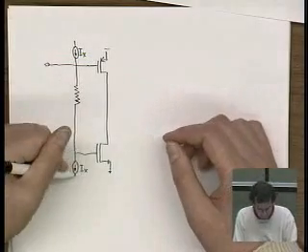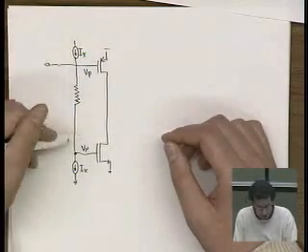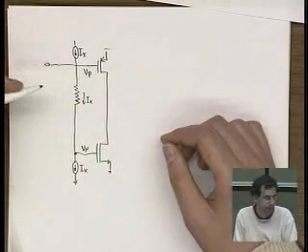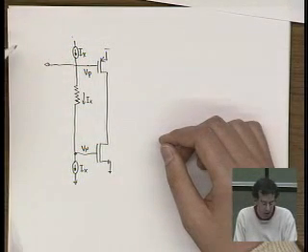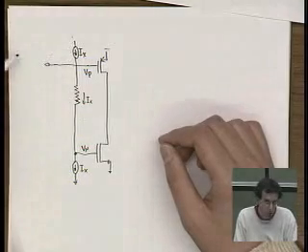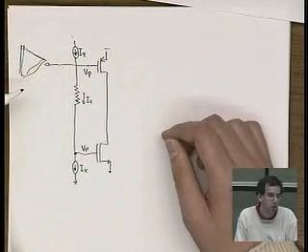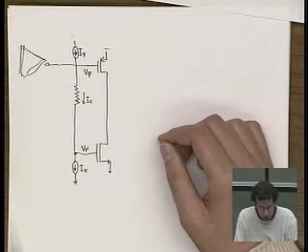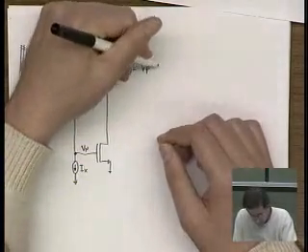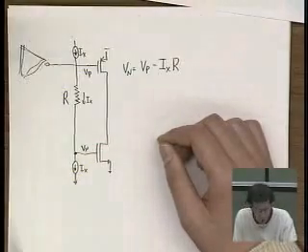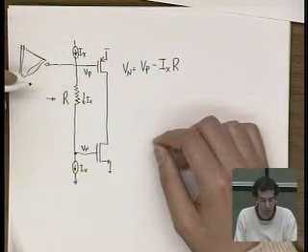IX, okay? So that being the case, let's call these VN and VP. We see that IX has to flow through here, and then it just gets sucked out by this to balance KCL. Now this IX on this node could be part of whatever the driving amplifier is. You don't need to explicitly put that here, but doing it helps keep things balanced. So that means, and this is R, VN is equal to VP minus IX times R. So you have a fixed battery voltage here, effectively.